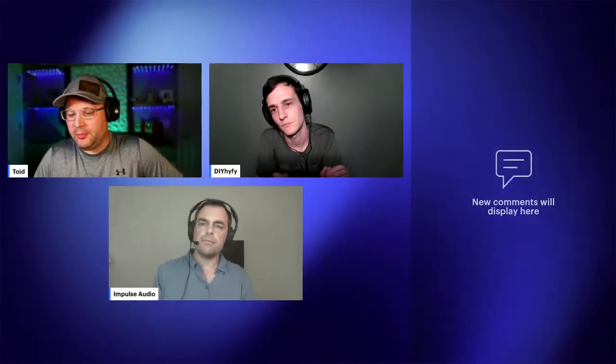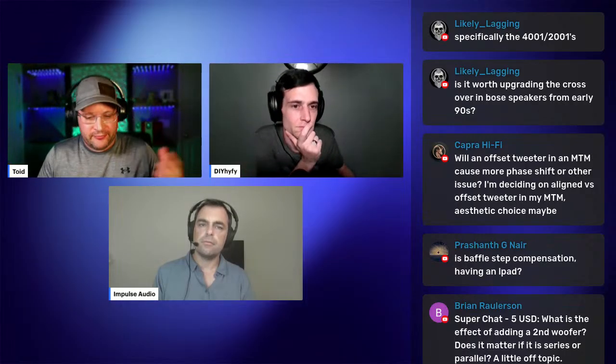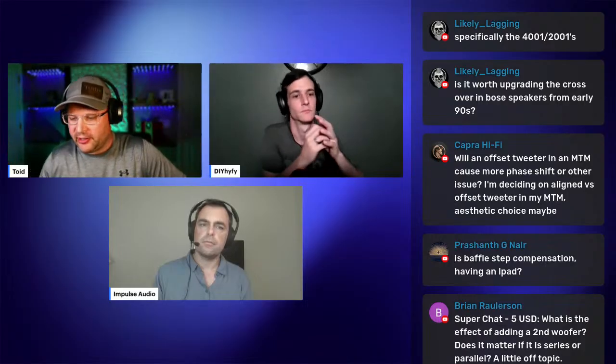This is the other effect. I think that those are probably just playing mid-range. And the tweeter is, Bose for the longest time did a lot of that reflective high frequency behind their speakers, off the walls. So I'm going to assume that those are mid-ranges and those are probably just a two-way design. And so once again, the acoustic center of those two woofers would be in between those two. That's why some people like an MTM, because the acoustic center is technically where the tweeter is, but you still have to design that correctly.